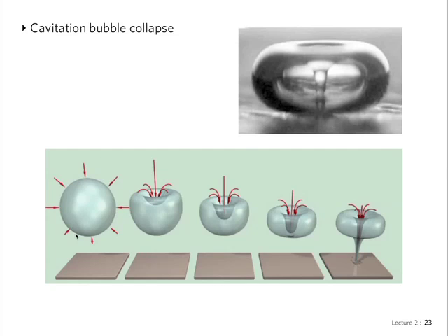What is happening is that the bubble was created at one point of low pressure, where the vapor pressure was reached. The liquid evaporated, it formed bubbles. Then the bubble moves to an area of higher pressure. So here you see the higher pressure squeezing the bubble in. The bubble buckles like you would, when you stand on a can of fluid. If it has a little wrinkle, you stand on it, there's a point where it just buckles.